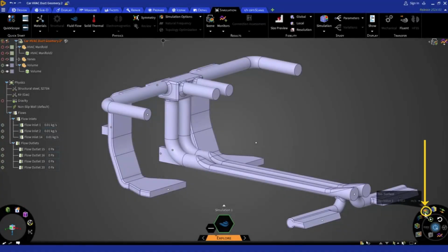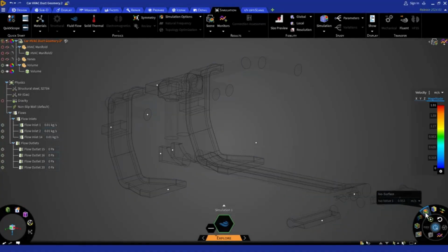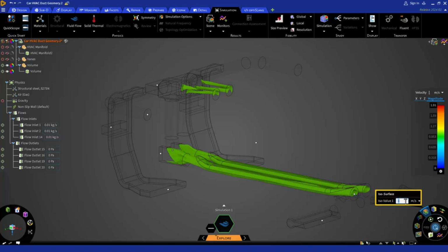Next, click on the isosurface icon. Isosurfaces allow us to visualize a specific constant value of a scalar variable. They can be used to visualize properties such as velocity, pressure or temperature in 3D space. In our submenu here, you can set the ISO value by entering any constant value and then hitting enter on the keyboard. You can also do the same with the provided slider bar.